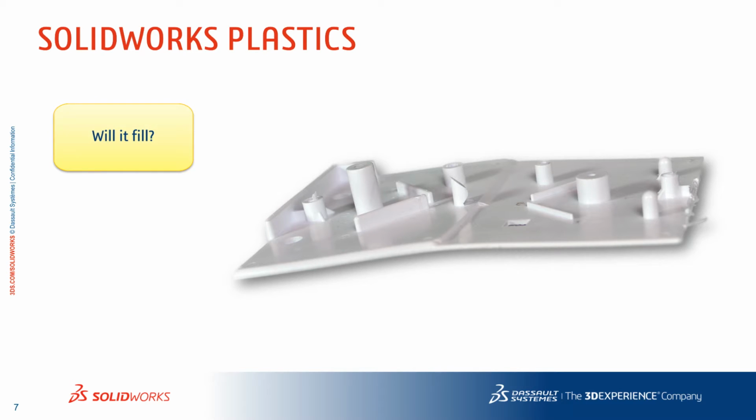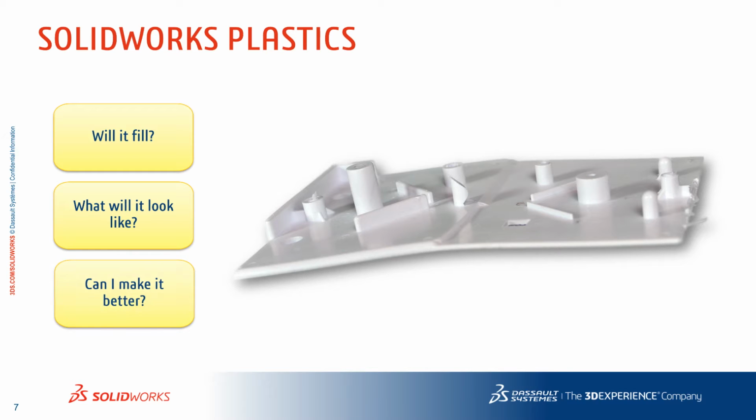Let's start with the most fundamental question: is this part even injection moldable? Will it fill? If it fills, what's it going to look like aesthetically and structurally? And most importantly, can I use that insight, that feedback from the tool to make my design better? When I'm interested in will it fill, I want to understand, are there nooks and crannies that I've designed where the plastic won't get to, but also understand what the cycle time might be for this part, or what kind of manufacturing capabilities I'm going to need.